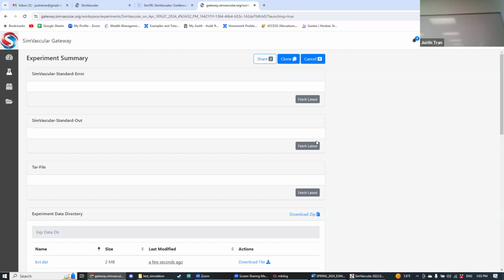We can try maybe some of the other smoothing options. The constrained smooth is the most stable one, because what can happen sometimes with the other smoothing ones is that the volume will actually decrease. So every time you smooth it, like let's say with the Laplacian smooth, it actually kind of shrinks the model a little bit. That's how it smooths. But if you do it once or twice, it's usually okay, but you definitely don't want to do it